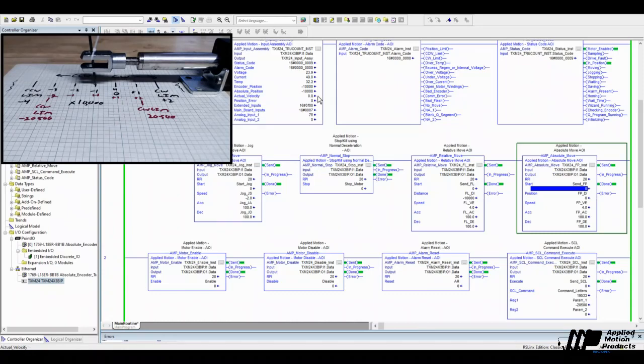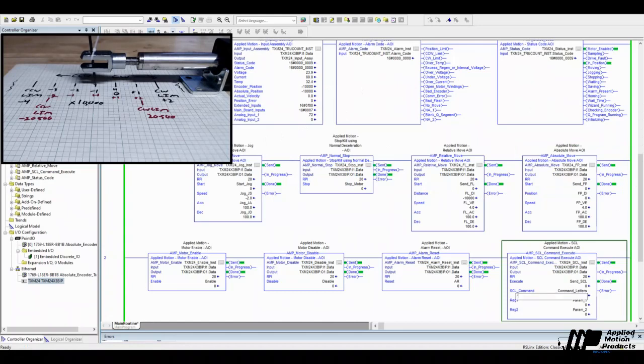So let's go through real quickly. We are at what we want to be our new home position. So we're going to send EP0, and we're going to send SP0, and we are going to send LM -20,500, and we are going to send LP +20,500. And now what we did not do last time, we are going to send SA with no parameter, 0.